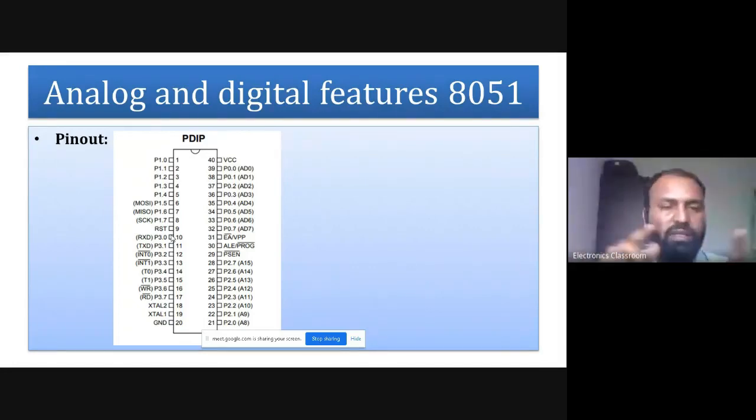be in the serial control register, and we need to enable the serial port. Whenever we enable the serial port, whatever application we are developing related to RxD, P3.0 is by default used for receiving data, and for whatever data we transfer, P3.1, or sorry, pin 11, is by default used as the TXD pin.